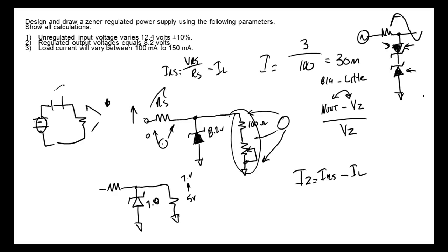So you see Zeners used in other applications besides a lot of clipping circuits. We'll see Zeners in clipping circuits. That's designed to just do what? Just to clip it off. Or in what we call crowbar circuits. A lot of times they'll deliberately blow a fuse in a power supply, to prevent from what? From burning up your load. And so if the Zener voltage is exceeded, it blows a fuse.